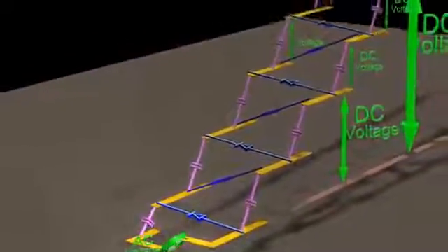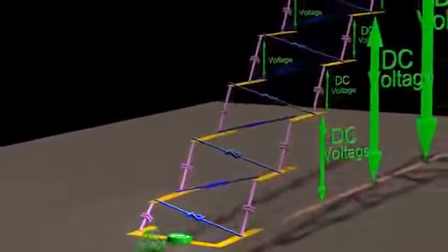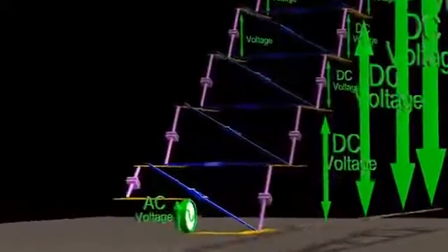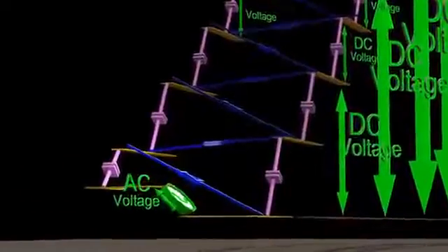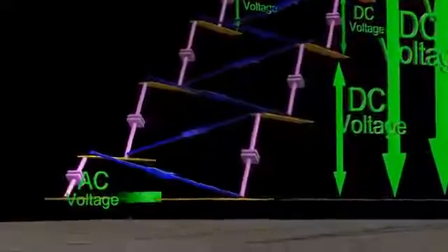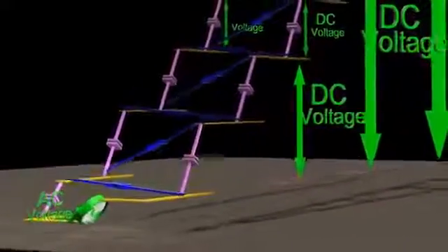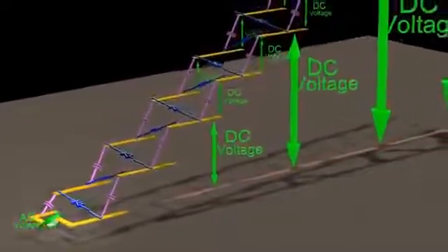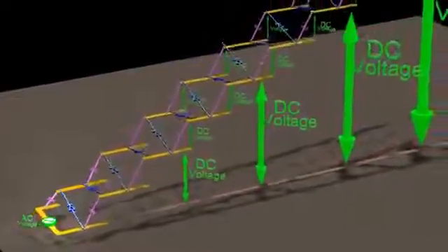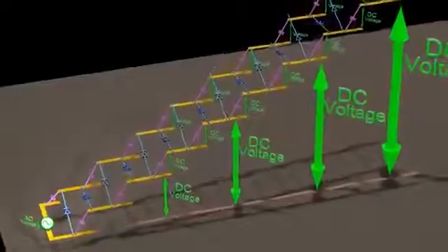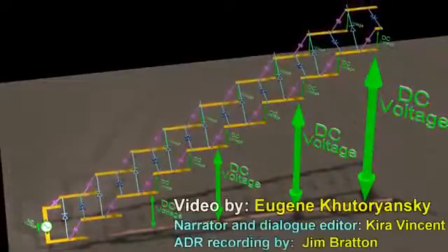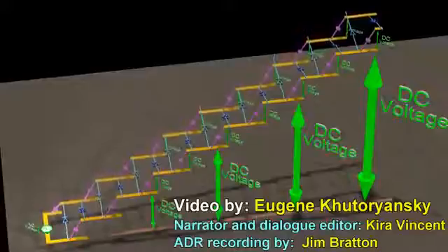However, this circuit is not capable of delivering a large amount of current to the output due to the fact that this would cause the capacitors to lose their charge, and the voltage would therefore go down very rapidly. But if we don't care about supplying current to the output, and we only care about creating an extremely high DC voltage, then this circuit is extremely useful.